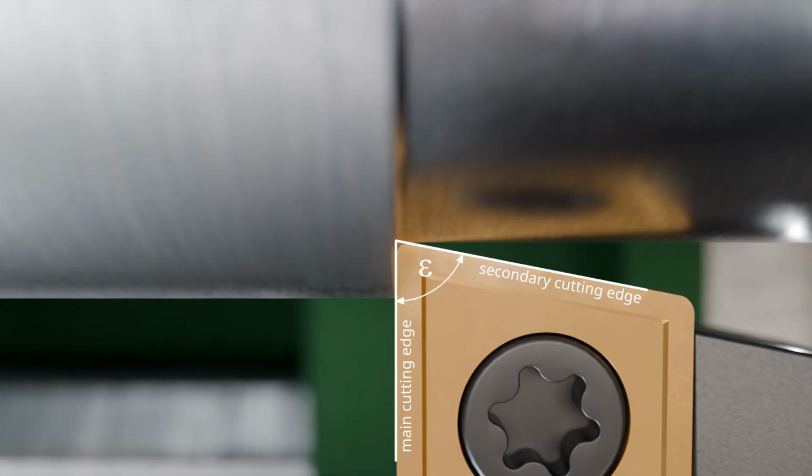The corner where the rake face and the flank faces meet is called the cutting edge corner. This cutting edge corner is not sharp but rounded for better stability of the cutting edge. The corresponding radius is referred to as the nose radius or epsilon or cutting edge radius. Large nose radii result in stable cutting edges and allow high feed rates and deep cuts, as required during roughing. Additionally, the large rounding improves heat dissipation, which positively affects tool life. During roughing, nose radii typically range from about 1 to 2 millimeters.